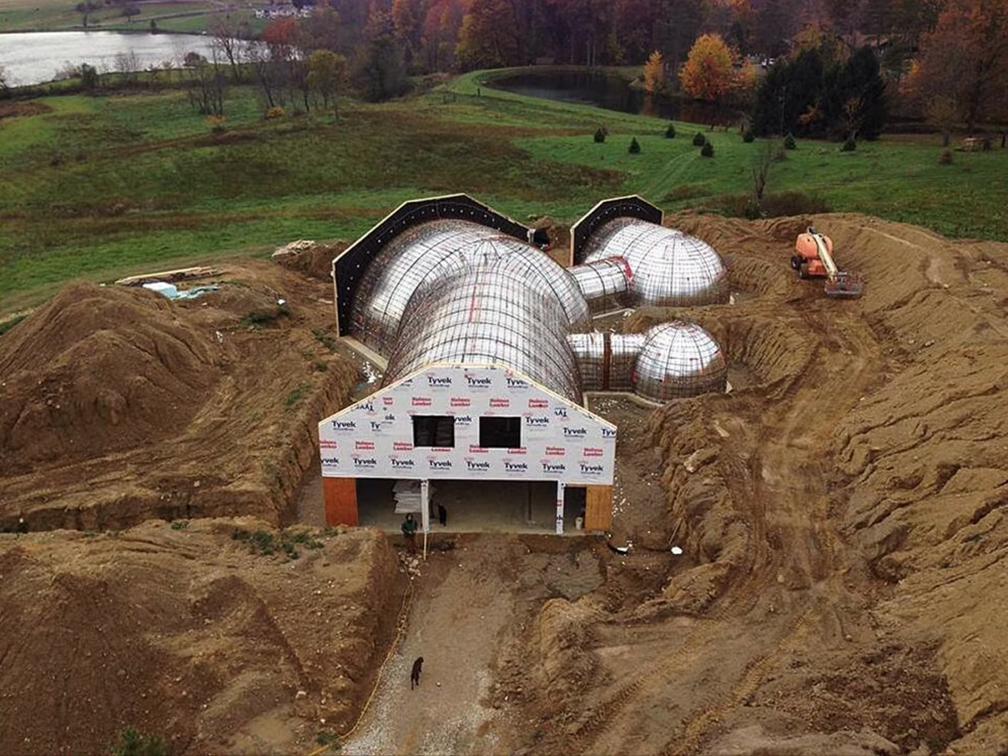And here is a prefabricated metal panel. So the metal panels are already prefabricated and they brought them out. And then they've excavated, and then they're going to cover this back up. And I will tell you, the two prohibitive things about this is it's very expensive to move dirt around, so you have to be really good at it. You want to do as little cut and fill as possible, but you're going to be doing a lot of digging. And then of course the other is waterproofing. Those are the two big challenges in this.